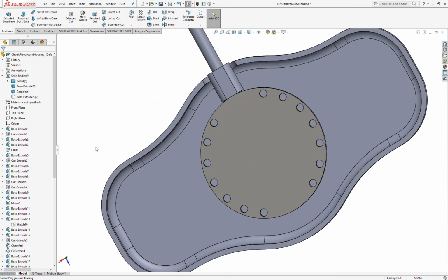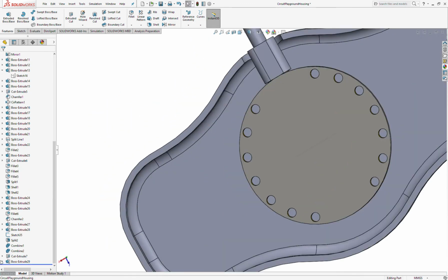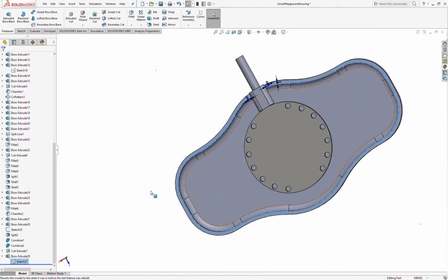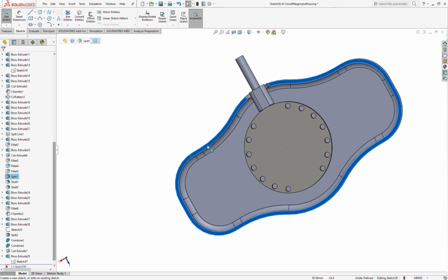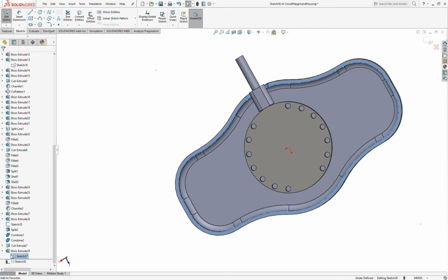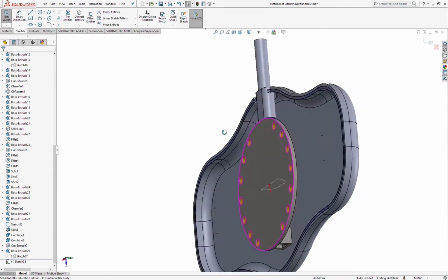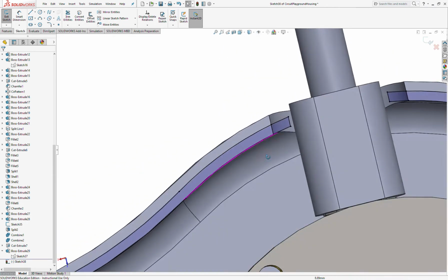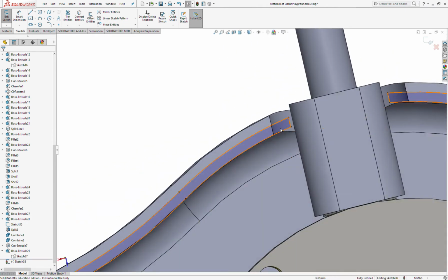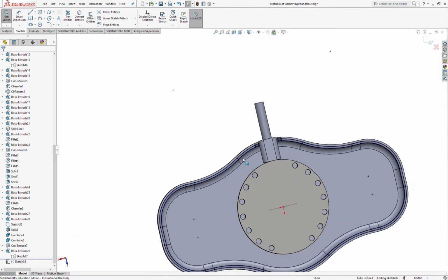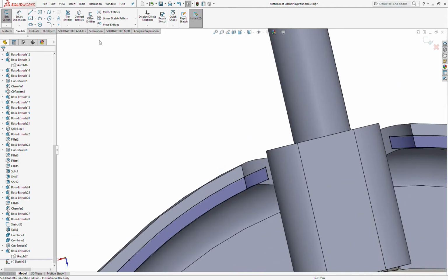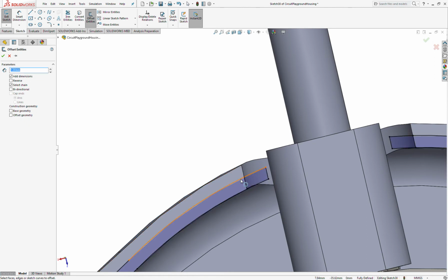And what's great with doing this sort of matching feature things, we can actually use this sketch. So if I sketch on this surface, select this sketch and hit convert entities. So that's where the other one is. So we know that we want it to be basically in the same spot, but we want just a hair bit more room.